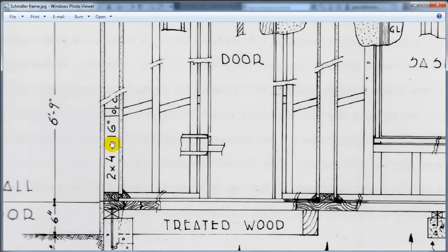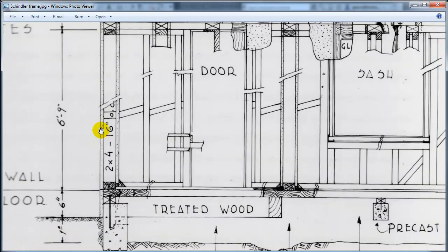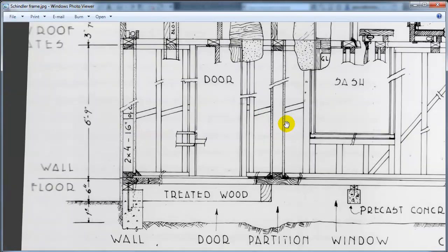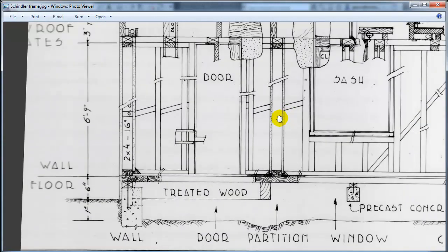I'm going to guess it's about 3.5 inches wide on the studs. Maybe it might have been a little wider when he built it. On the outside, I'm going to guess maybe 3/4 for the stucco and maybe about 3/4 for the interior, but it might be a little bit different. There's another base wall case over here, the interior wall condition, and that again would be about 2x4, 3.5 inches wide, then maybe 3/4 and 3/4 for just plaster on both sides. So we'll create one that looks like that too.